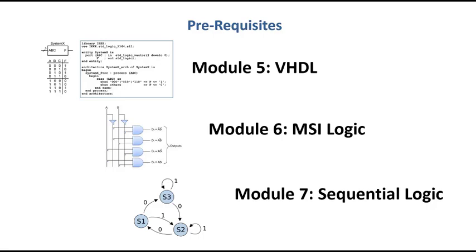So if somebody said build a multiplexer, all you really need to know is how a multiplexer is supposed to work, create the truth table, and then synthesize the logic using a Karnaugh map. Or you could, if you knew how it worked, you could describe the multiplexer in VHDL and synthesize it using an automated CAD tool. Finally, we wrapped up with sequential logic.